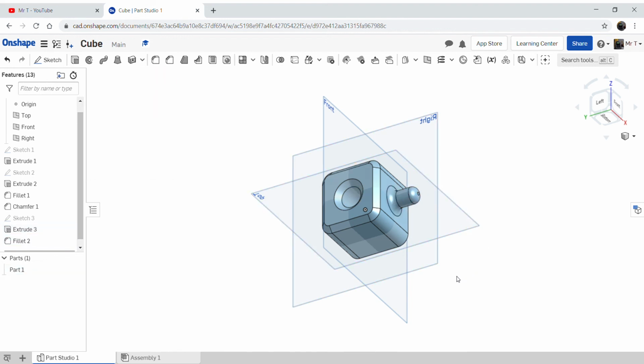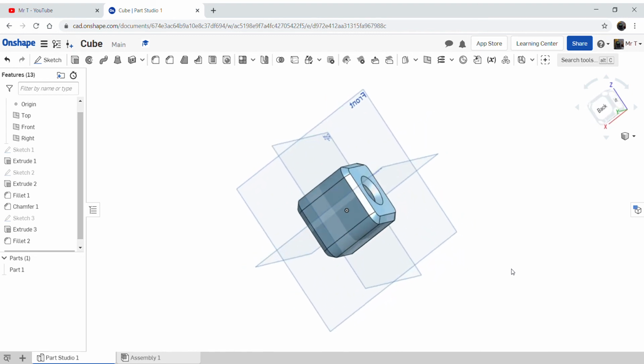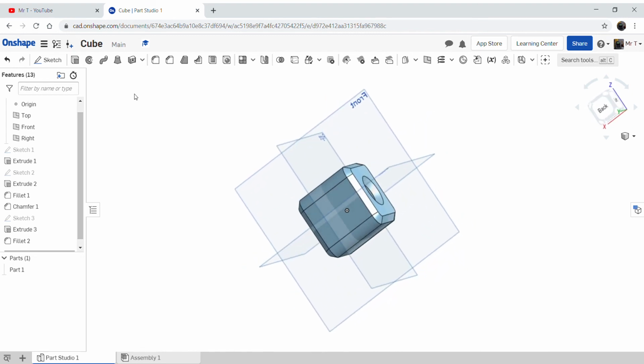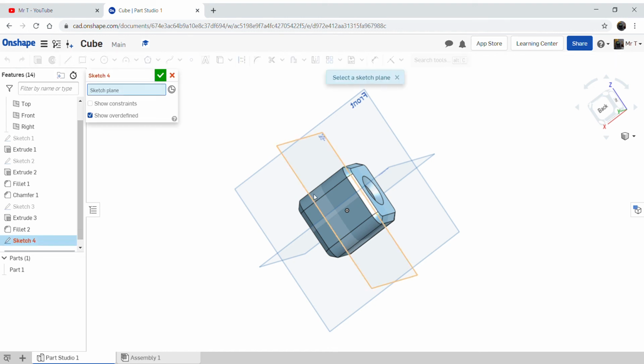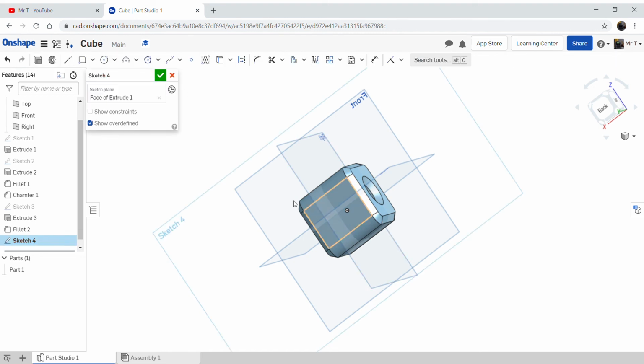Okay, and we're just going to practice that, so we're going to spin around and do exactly the same on the other side. So we'll go to sketch, select the plane we want, select the tool we want, find the middle, which it does for us, pull it out to roughly 15, well it's not 15 but still, press D to dimension, select it, drag away, and 15 is the diameter we want. So that's all sorted. Select to accept that one.